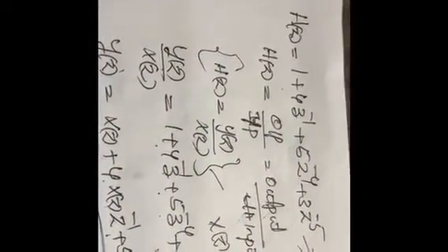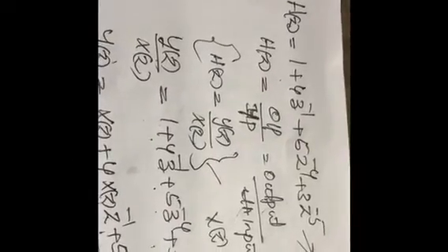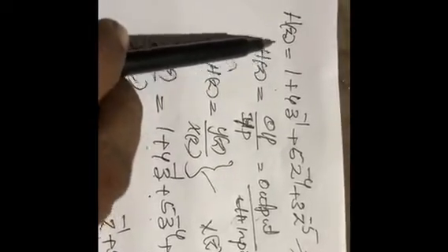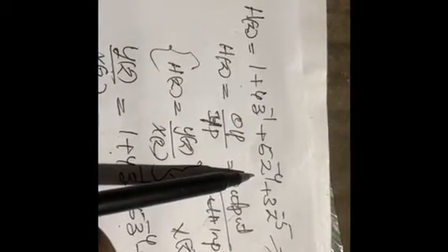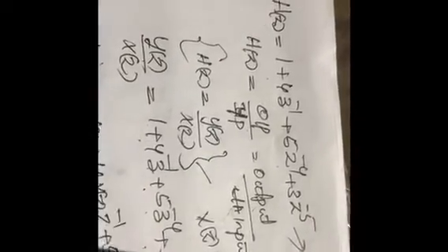Here I explain the FIR direct form structure with an example. For example, I use the transfer function or the system response H(z) = 1 + 4z^-1 + 5z^-4 + 3z^-5. From the definition of transfer function, we know that H(z) is equal to output by input.